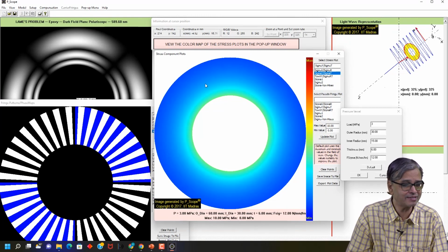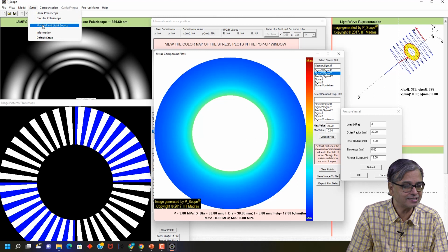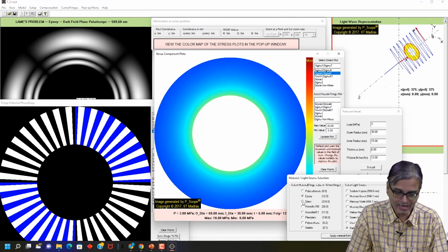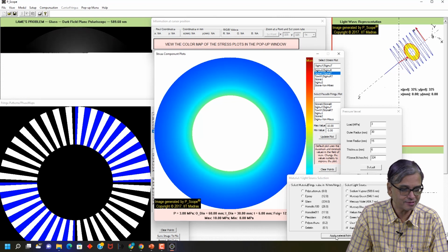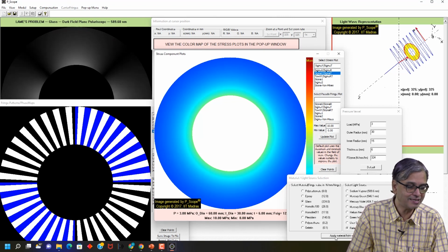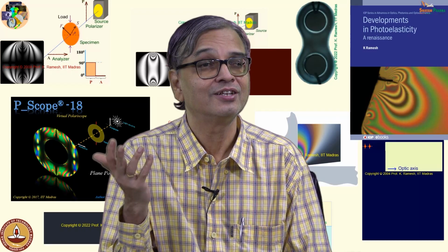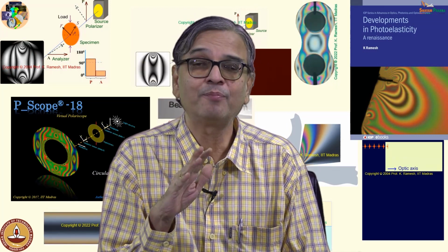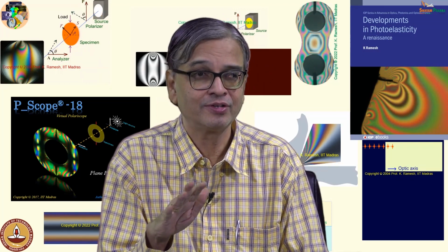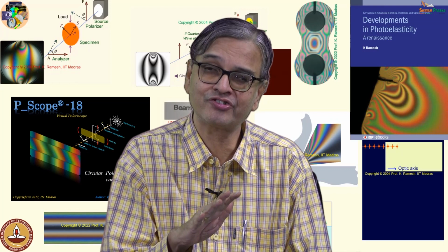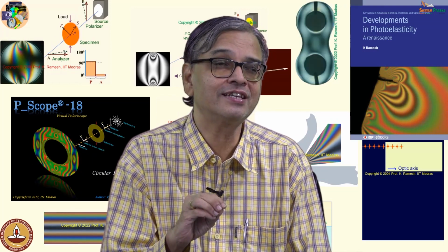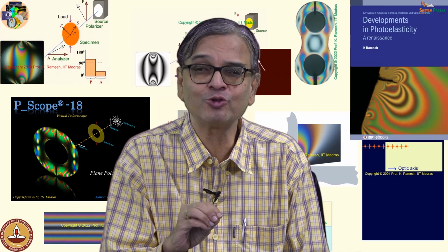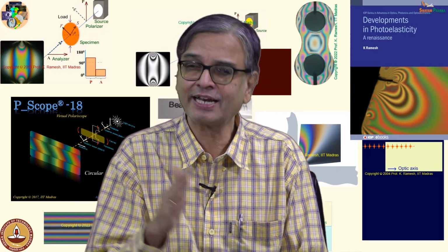And we have also been seeing glass. Okay. So, we will also change this to glass and then see. So, if I go to glass, what happens to this? I hardly see any fringes, fine, but the stress magnitude, do they change? They do not change. So, in linear elasticity, when the body force is constant or 0, for both plane stress and plane strain, photoelasticity gives the stress magnitudes which can be correlated to your metallic prototypes.